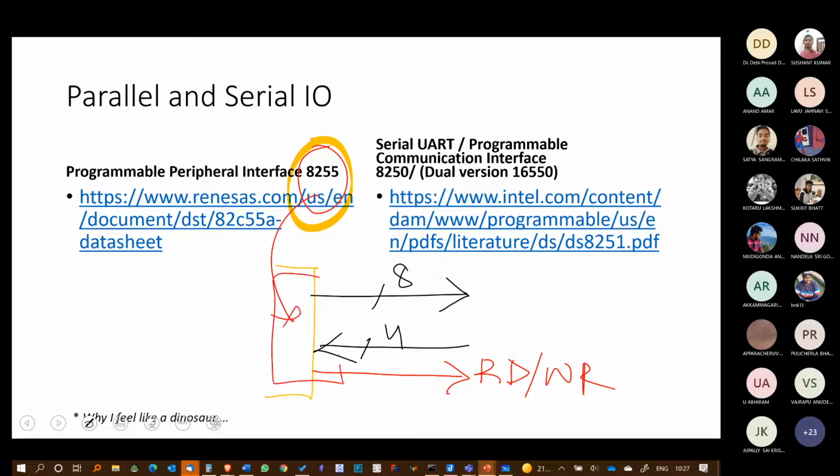You can put an 8255 here, and like any other IO device, it will have data, status and control registers inside. You can program the 8255 and say, give me one port which is output and 8 bits long, and give me another port which is 4 bits and input. That is done by programming the control register of the 8255.